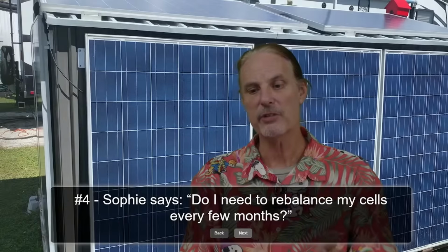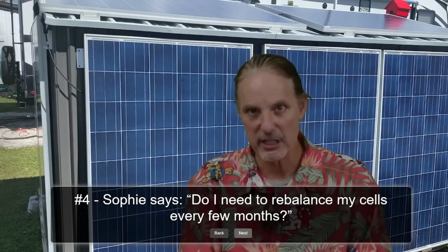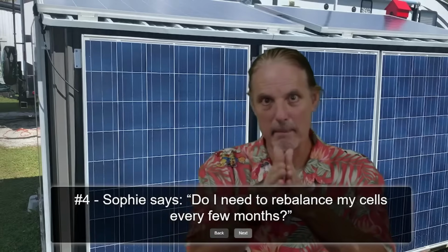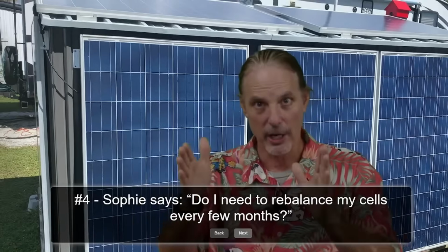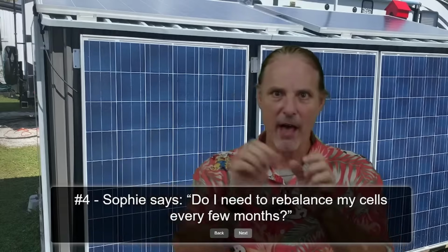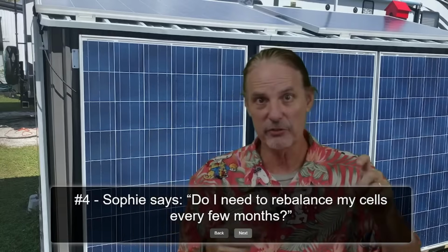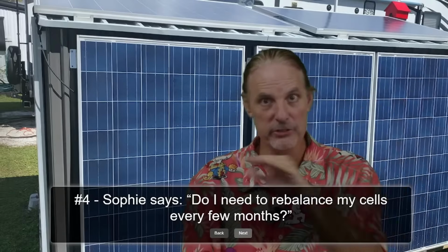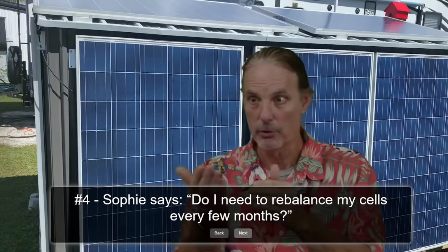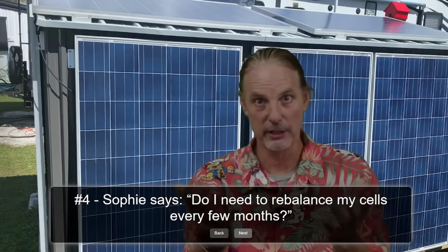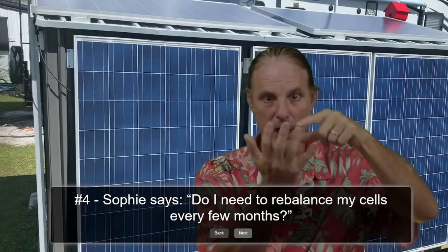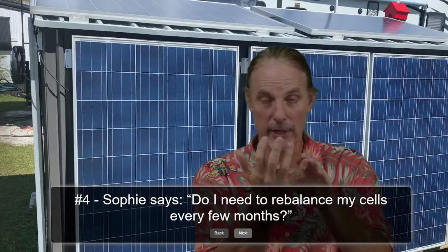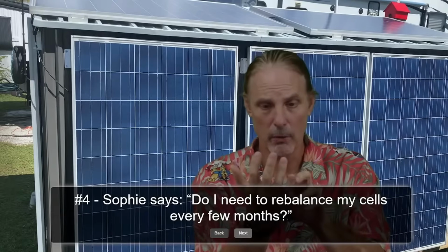So that would then start to do that balancing at that point, and that's when you need to stay in that balancing area long enough to allow that battery to, in a passive state, burn off that excess from the high voltage ones and then replace that with new power coming in to charge up all of the cells again and keep burning off on those high ones until all of the batteries are brought up to the right thing. And in passive mode, that can take a while.